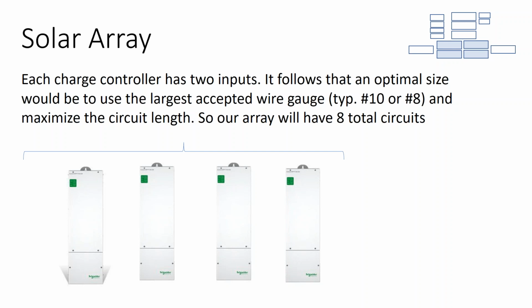In solar design, you're often upsizing your cables in order to reduce resistance. Resistance has an even larger impact on batteries than it does on solar. With solar, the more resistance you have, the less efficient your system is, and that means you produce less revenue. So you upsize your cables to make more money.